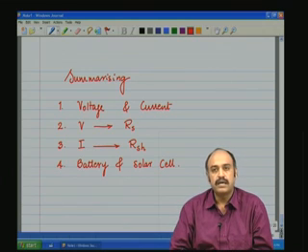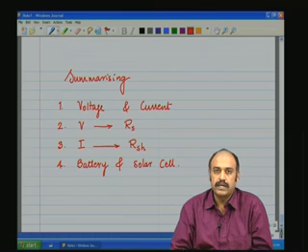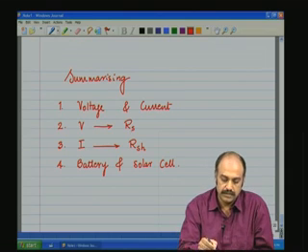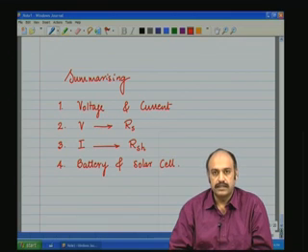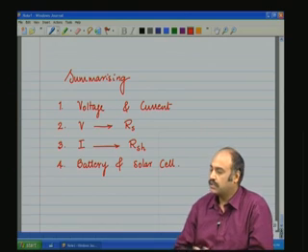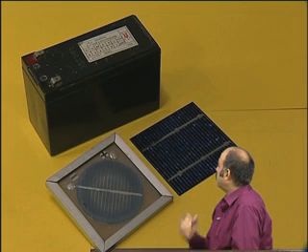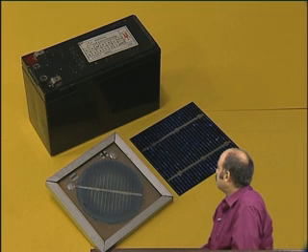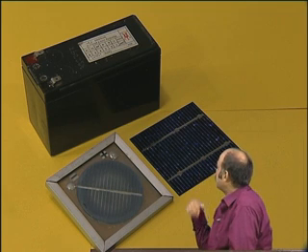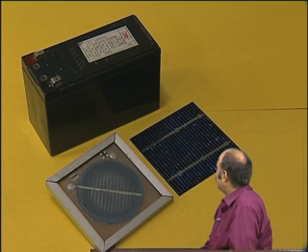That is, it could be an equivalent series impedance instead of just an equivalent series resistance in the case of the voltage source, or an equivalent shunt impedance instead of a simple equivalent shunt resistance in the case of the current sources. And of course, we did have a close look at these sources here, the lead acid battery and the polycrystalline, the monocrystalline solar cells.